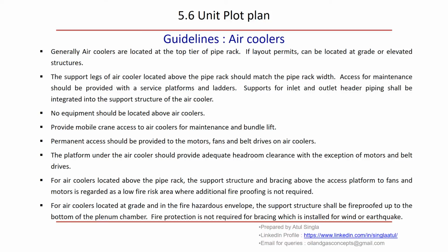Provide mobile crane access to the air cooler for maintenance and bundle lift. Because these are air coolers, there will be tubes, and we have to do the maintenance. Sometimes we have to pull the bundle out. For that we have to provide access.